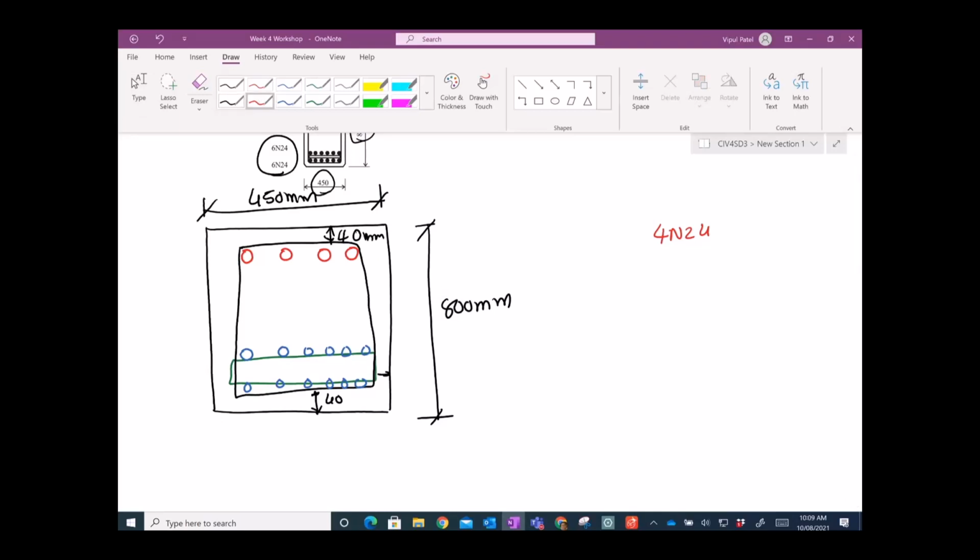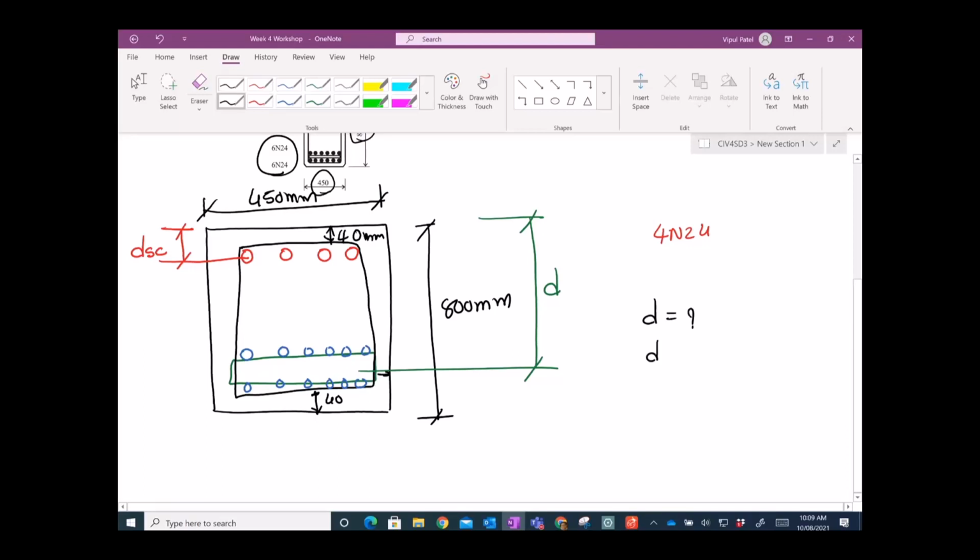So I think you know that drill, that you need to calculate this distance. For any reason you need this distance, and we need this distance as well, that is small d, right? So for any calculations we need those. For any beam, you need small d. If it is doubly reinforced, you need dsc, you need alpha 2, you need gamma. Those are just by default. You need dn, you need Ku, you need Ast minimum, you need minimum moments. Those are the typical recipes for the beams.